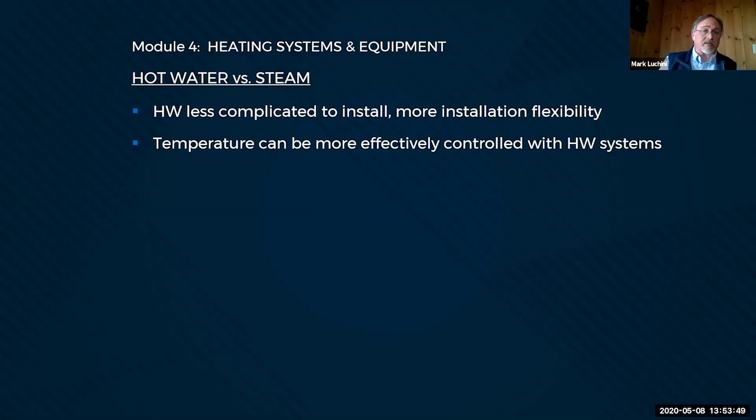Yeah, and they're just easier. Hot water is a lot easier to install. Your pipes can move up and down. You don't have to worry about pitch, any of that. It's also easier to control temperature with hot water systems.